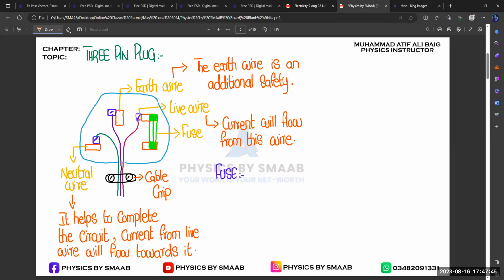If you just observe this fuse, you will also find that into the plug of that refrigerator and in a microwave oven. Sometimes it is covered with like the opening rubber or plastic thing, so fuse is inside it, so we just need to replace that fuse if something is not working. Like if we just plug in a wire and that wire is not passing the current, first we need to check the fuse, that either fuse is blown or not. Because if fuse is not correctly connected, there will be no current into the circuit. So first of all we need to check the fuse, right? So basically it is a safety component.